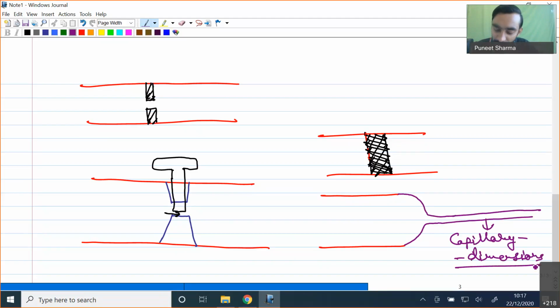So this is also a device where, while the flow travels from the bigger tube to the smaller tube, we have a significant decrease of pressure. This type of device can be seen in our refrigerators and air conditioning units, after the condenser, where our saturated liquid refrigerant is expanded through this, and its temperature decreases at the same time. Some fraction of this liquid refrigerant converts into vapor also.